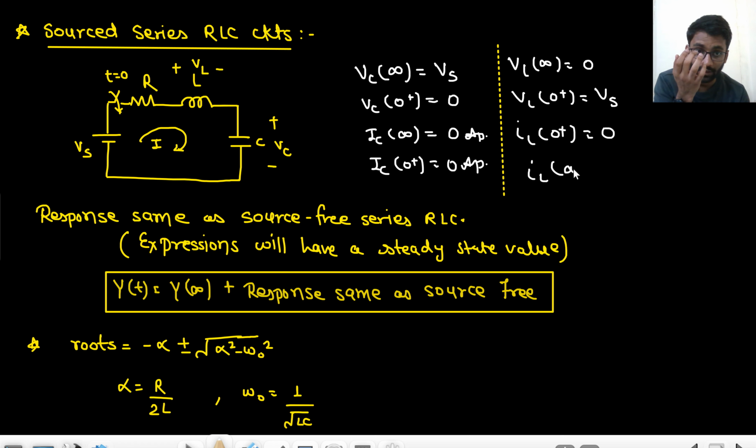And what is IL infinity? That is also 0, because at infinity the capacitor will be open circuited. Let's assume you are writing the expression for VCT.